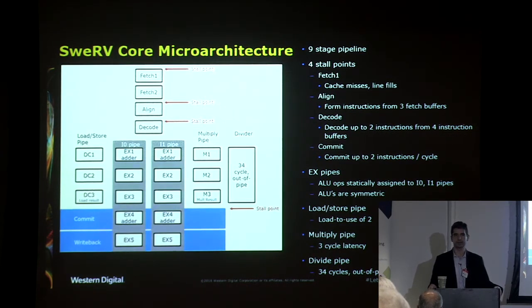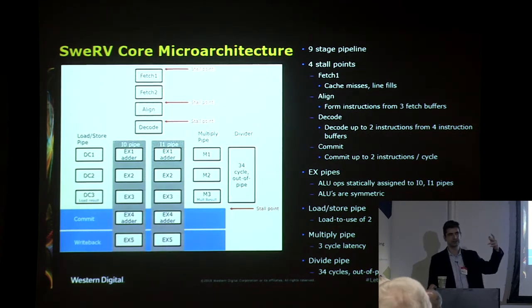The second question is, why do you need an aligner? An aligner is needed because the compiler tool will generate, and we'll see later how good, compressed instructions. So you'll have this flow where some instructions are encoded as 32 bits in memory and some are 16. So you need to have an entity in the pipeline that's going to discover the beginning and end of instructions and then unpack and understand the compressed instructions.